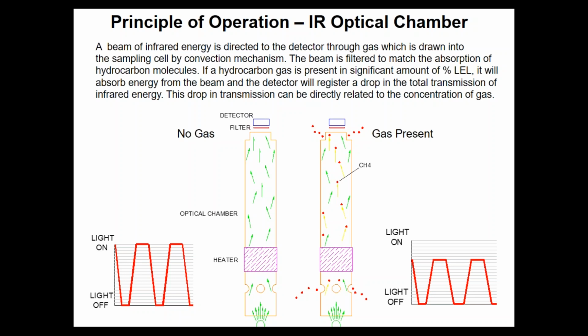So what we have done is we've come up with a method that allows a detector on one end and a light source on the other. The light source outputs what we call a white light. It's a broad spectrum of light frequency that hits your detectors. And those detectors are set up with a filter to see a specific wavelength.